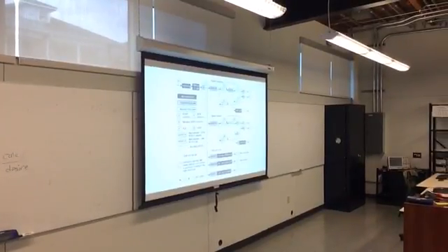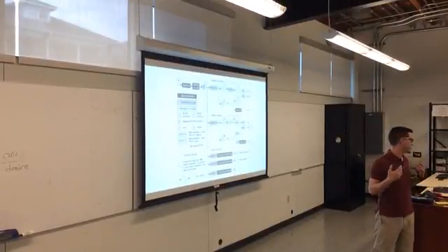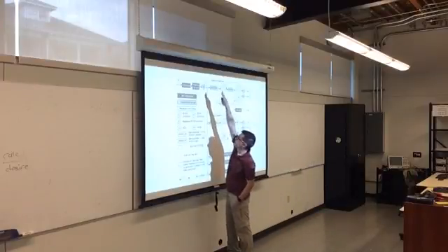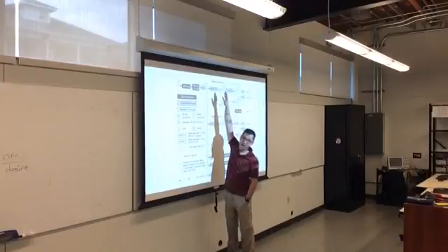If you happen to see a different number, then that means you're in a different state. But the idea is that once you transmit a start bit, you then need to transmit an 8-bit packet that has the address with a write bit. This is if you wanted to write data. You will then wait for an acknowledgement.